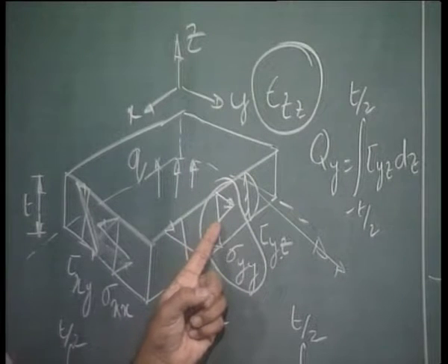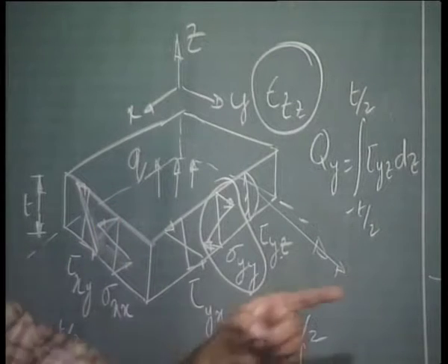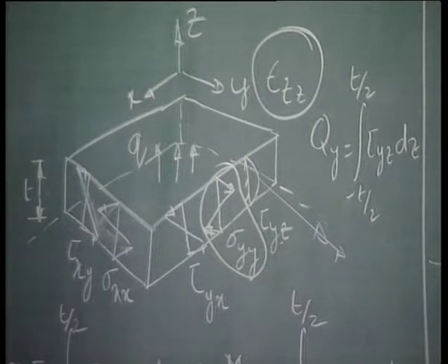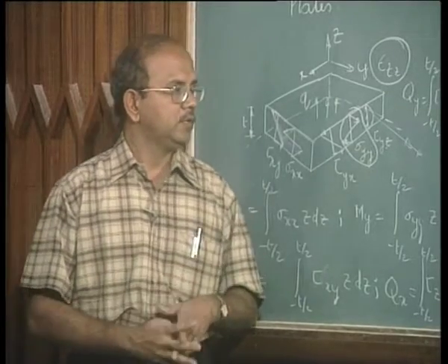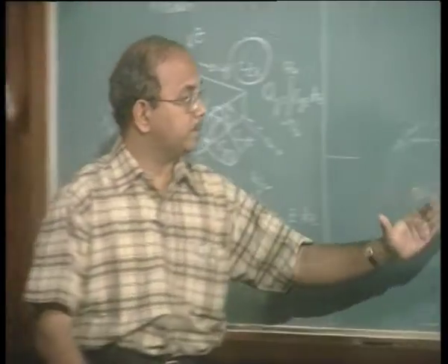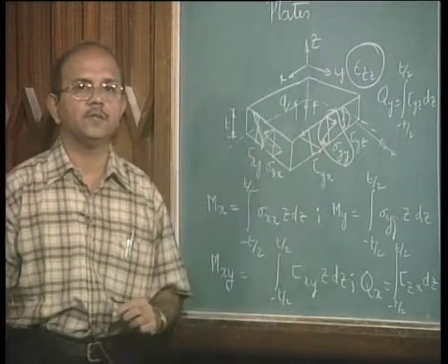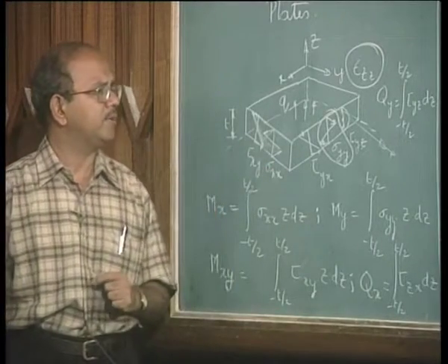That is the difference between the two. Look at that: the stress is 0 at the neutral point, which may not be 0 when we include plane stress behavior for a shell. In fact, this plane stress behavior most of the time may even dominate the bending behavior and take the load. Please note first that in plates we do not have plane stress behavior, and that gives us an interesting possibility which is exploited by many packages.